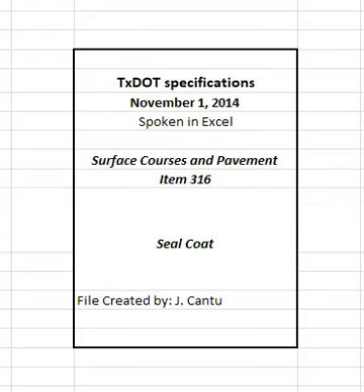Furnish a volumetric calibration and strap stick for the distributor tank in accordance with Tex-922-K, Part I. Provide documentation of distributor calibration performed not more than 5 years before the date first used on the project. The engineer may verify calibration accuracy in accordance with Tex-922-K, Part 2.